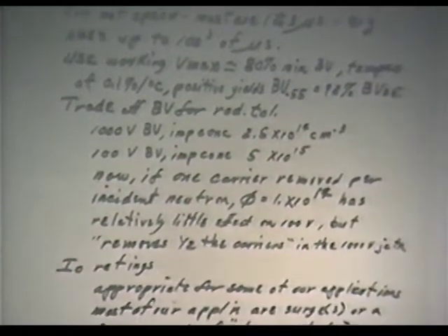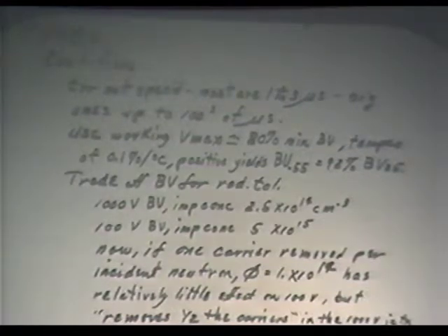I went through a number of types here. I'm not sure how much profit is in that. I don't plan to read all that to you. But generally, for the classification of rectifiers, at least in the data book, they do not specify recovery time. Implication is these are gadgets that are used at line frequency, and most anything is good enough, if there is nothing done to speed it up, and if it's a reasonable sort of a device, and that's hard to follow up and say, what do you mean by that?